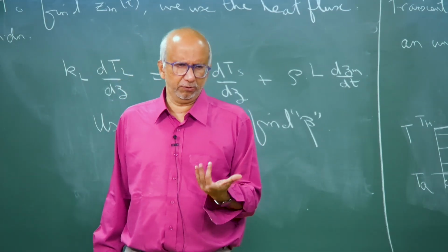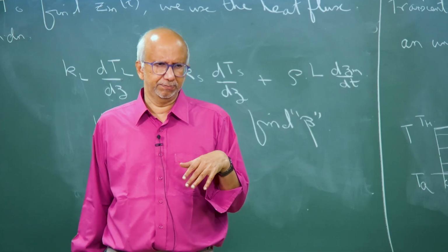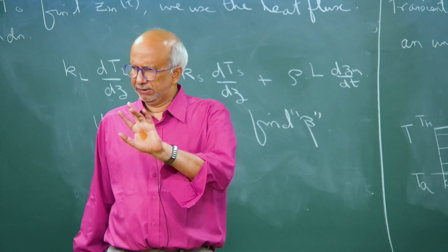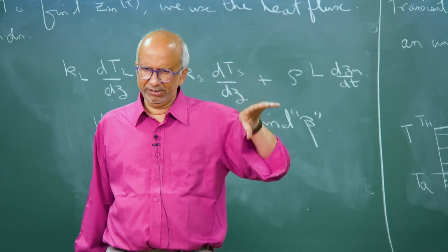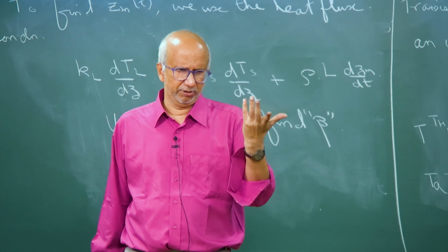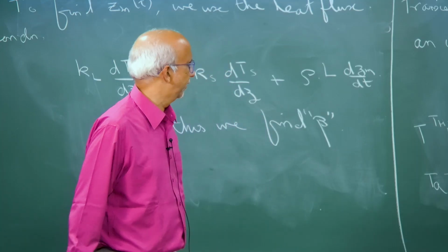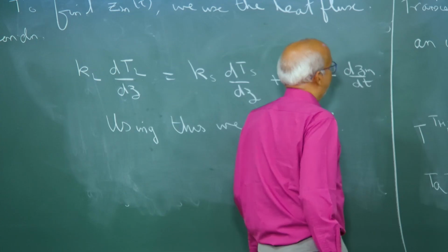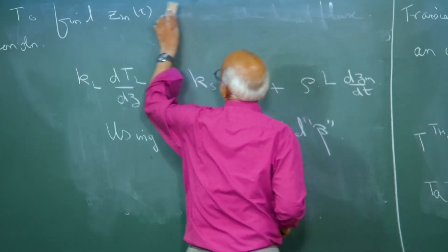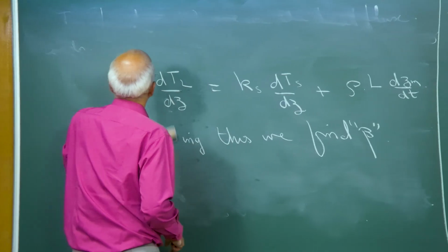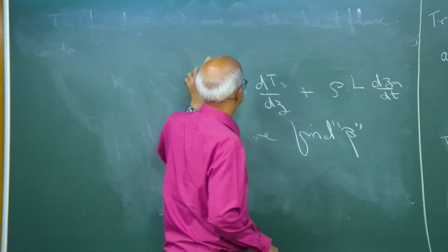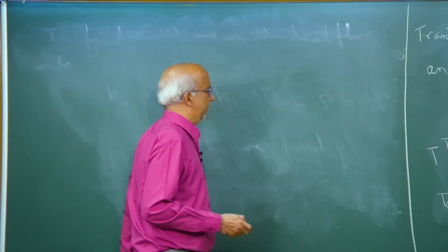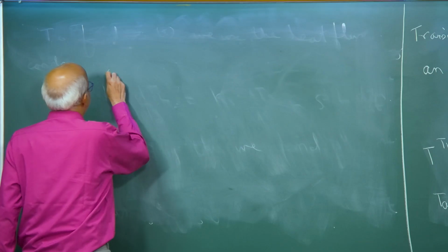What we want to do is we want to quantitatively understand how does this change. Okay. So, temperature clearly is a function only of r and t. I am assuming that it is one dimensional, no variation in the theta and the phi direction, and we are working in spherical geometry. Okay. So, again our objective is to find T of r comma t.